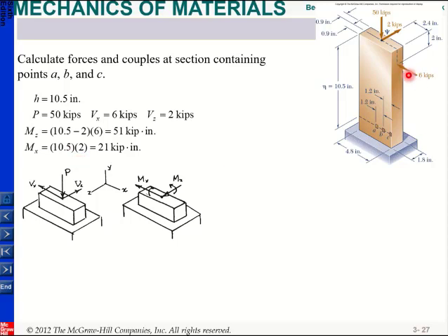And then I also have this force, so this is parallel to the x direction and it passes through y, so it does not create any moment on x and y axes, but it creates a moment along the z direction, okay. And since it goes this way, it creates a moment along the minus z direction. So, its magnitude is the distance from here to there, okay, times its magnitude.